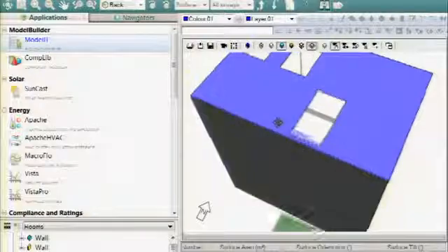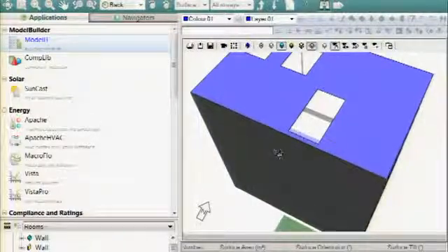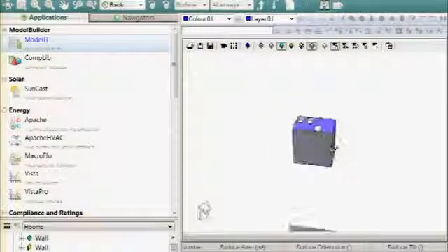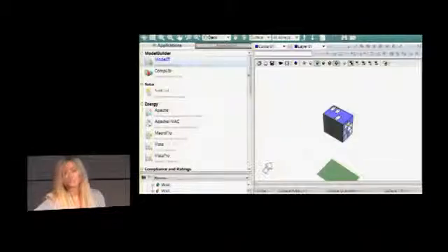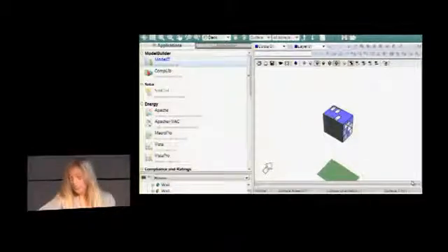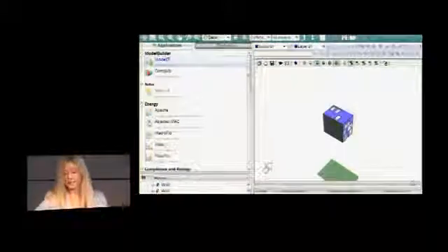In this case, you can see this is a perfect example of that, where it's actually above the ground here. It's because they put in the actual elevation for it, so that needs to be moved back down. But in Revit, since you're going to set your constructions and everything when you go into IES, and the adjacent temperatures, all of that's important. It's just making sure that your model's at 0. Anything that you build below 0 will be below grade inside of IES. So you're just building it the same way as you would build any other room, but below 0 elevation.